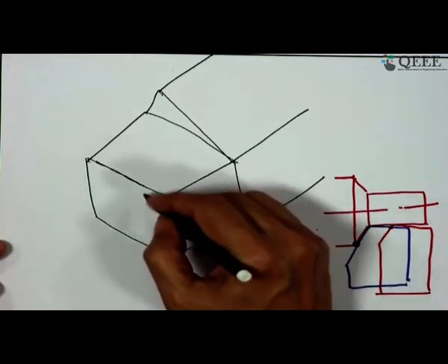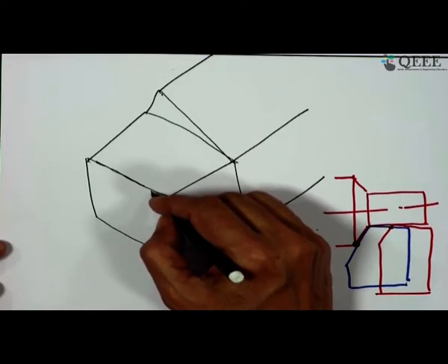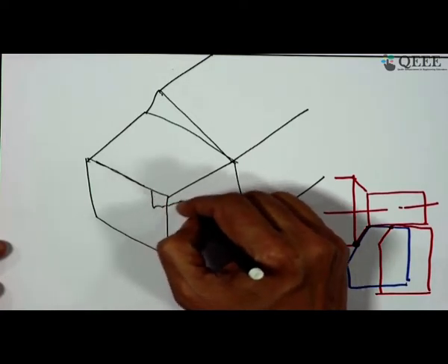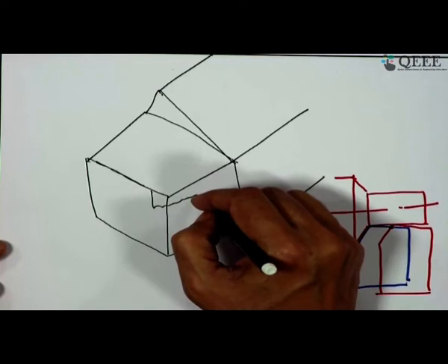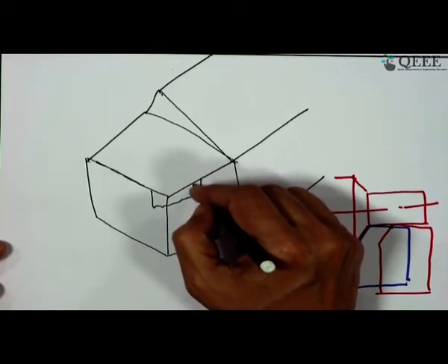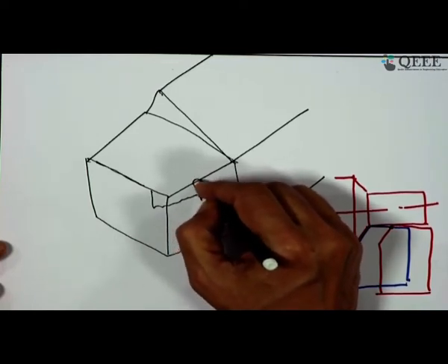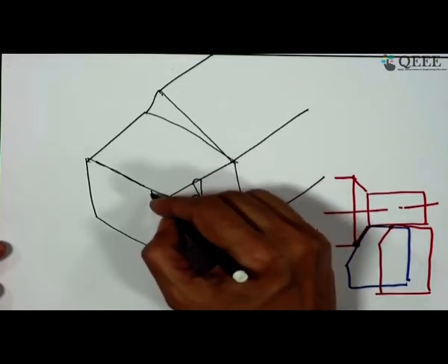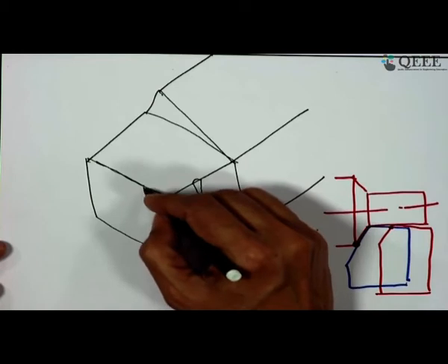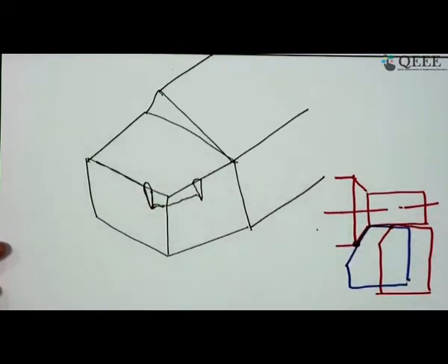So, I have already shown you that this is the flank wear, this is the flank wear and that is the border, but here what do we find? We find a V notch, it is almost a cutting knife. So, with that we have a notch formation, and where does this notch form?